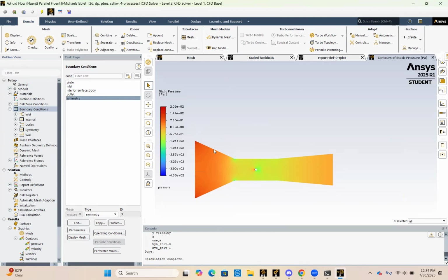I'm using viscous flow, so it wouldn't make sense for me to do that, unless for whatever reason I wanted to see the no slip on the circle but was okay with slip on the edges. I just named it symmetry for simplicity to combine it, but in this case I'm actually going to move it back to wall. Wherever wall went, it should be at the bottom, sorry.